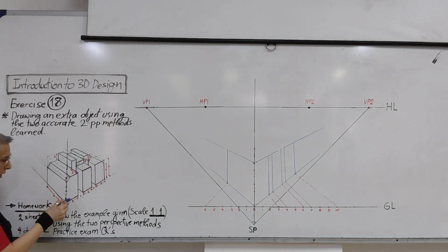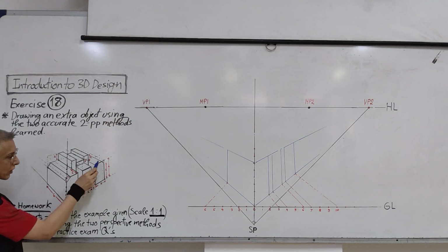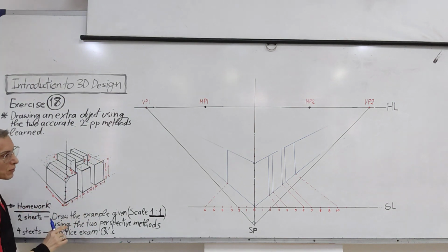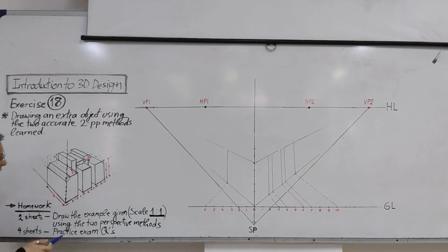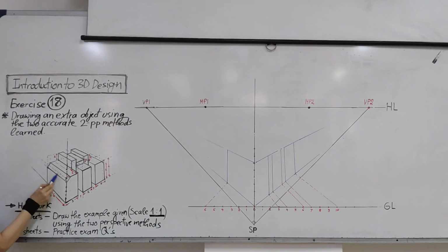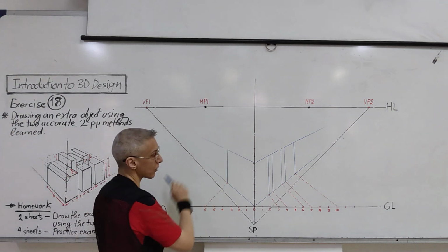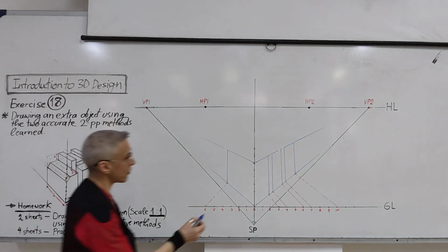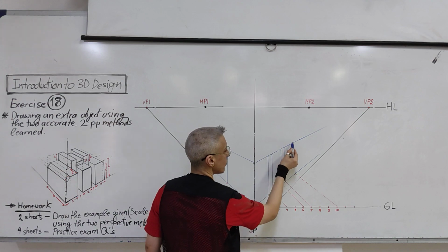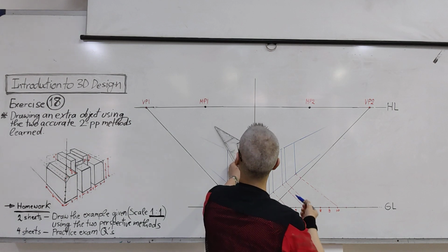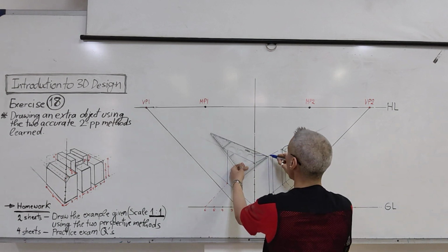Okay, now, these, for example, 3 objects, are they all the same height? Yes. Okay, the entire height, 6 centimeters, so all of them will have the same height. From here, 6 centimeters, we already found it, the height of it. Okay, if we consider it as a cubicle. So from here, also 6, so it will intersect with this line. So this is the height. Now, from all of these points, which is this point, this point, this, we will take to the vanishing point to complete our object. So we will take it to where? The vanishing points.